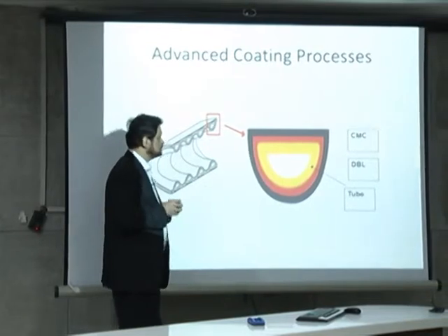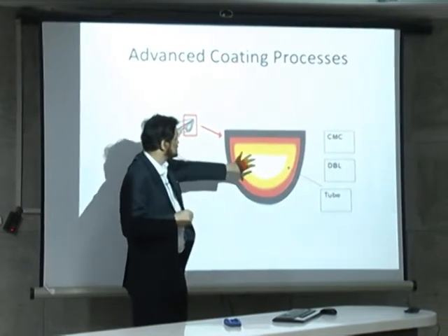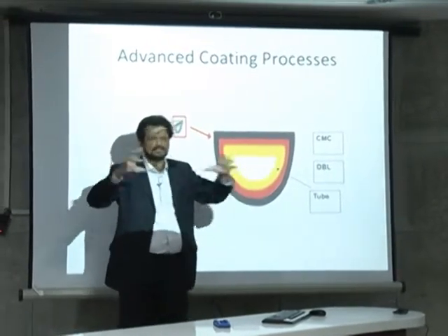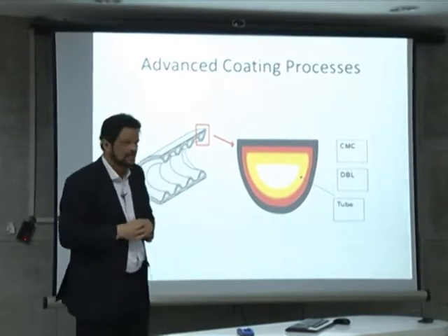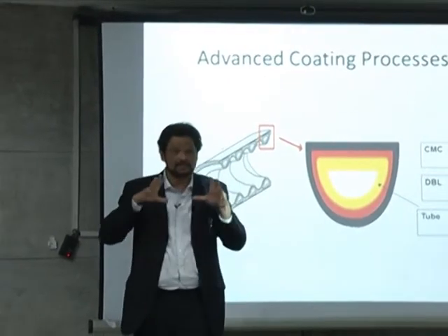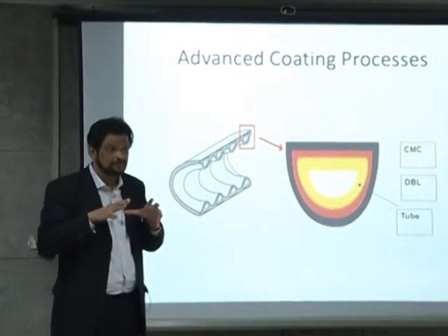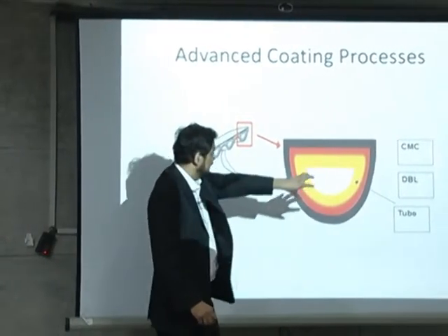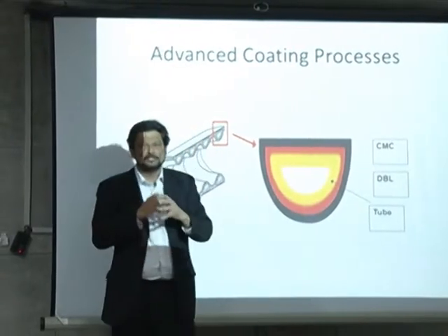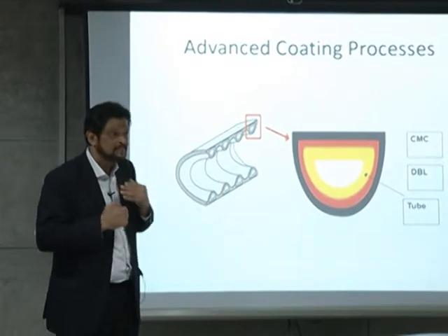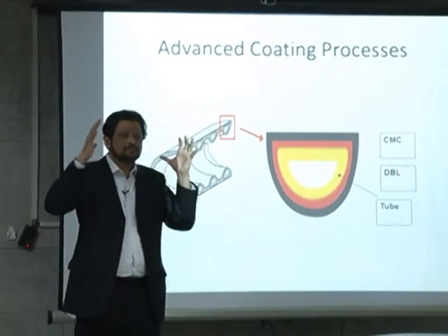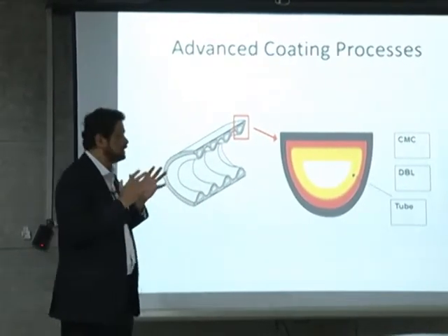Now the problem is, and there are multiple problems, at very high temperature ceramic will start, let's say we make a tube of some material, some rhenium, titanium, whatever metal. The ceramic starts dissolving literally into the tube. At the same time, the inside fluid starts corroding the tube surface. So typically what you want is something that will keep the dissolving of ceramic away.